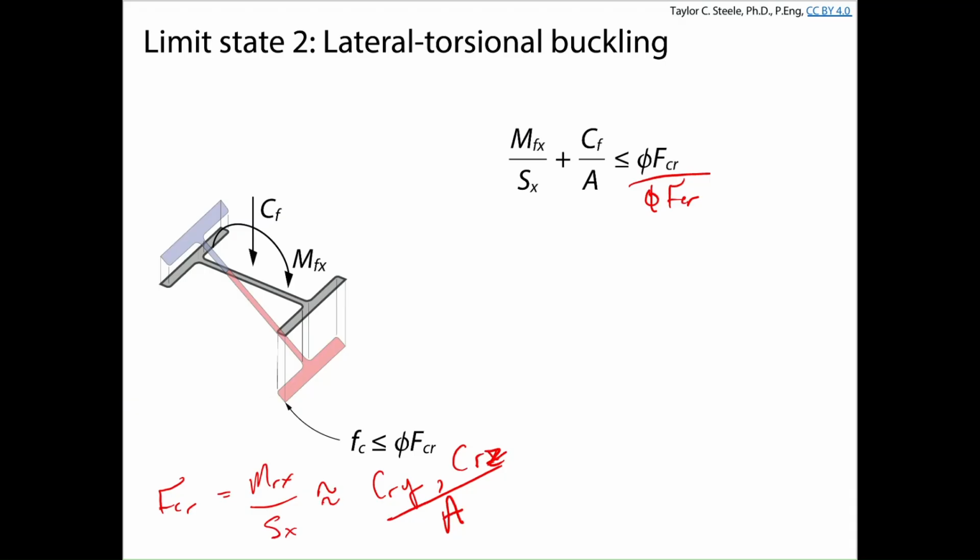Okay, so whatever stress on the cross-section would cause weak axis or torsional buckling, whichever is critical for the boundary conditions, we're going to assume conservatively that that stress is equal to the same compressive stress that would cause lateral torsional buckling. They're similar, right?